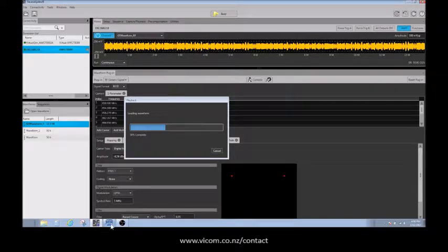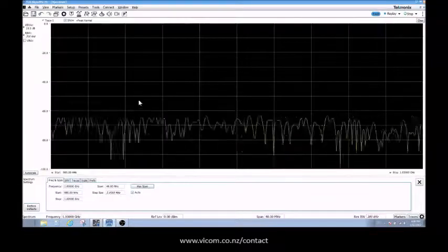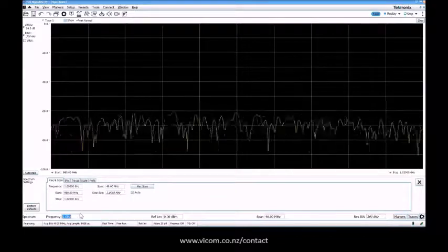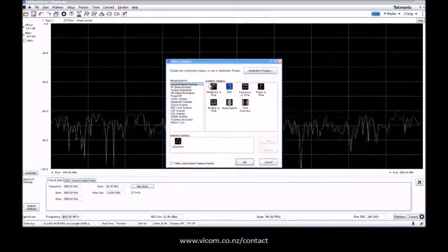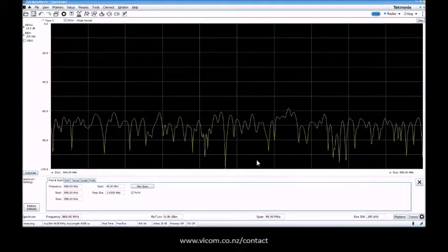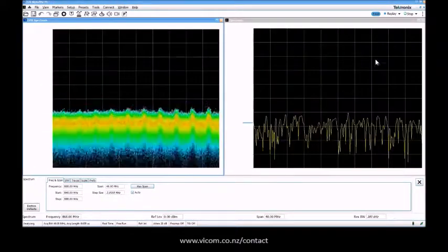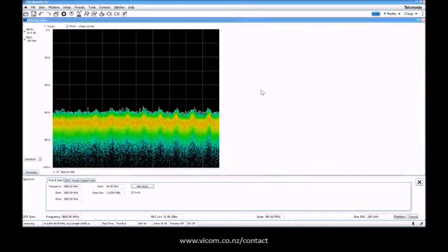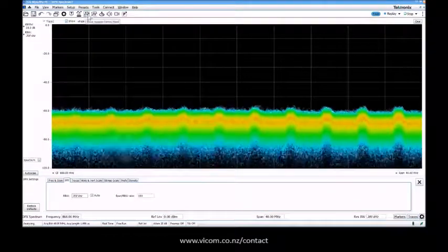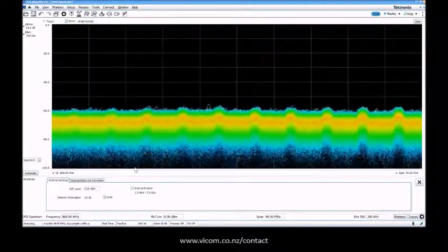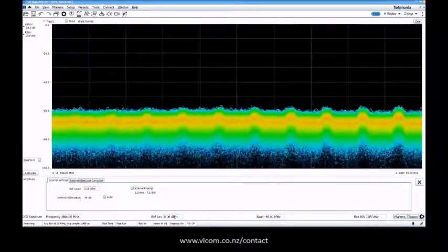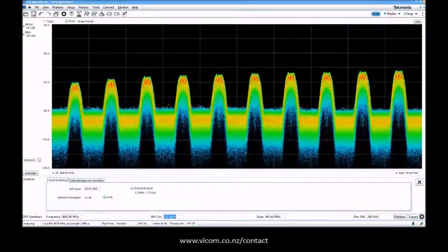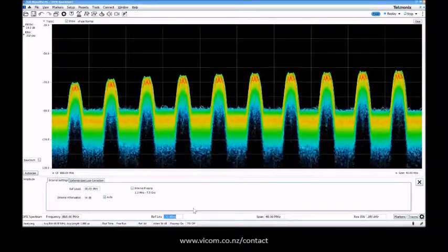So now I'm playing. I have a small antenna here in my lab, and I go into this one. So we have 868 megahertz. I'm going to only use the DPX. It's kind of neat to look at. You know, I like it a little bit better, so we move this around. There are a few tweaks here. First, the amplitude. The 507 has a controllable preamp, so I will just put it on, and then we go down to where we have something. Yeah, we have a decent signal at least.